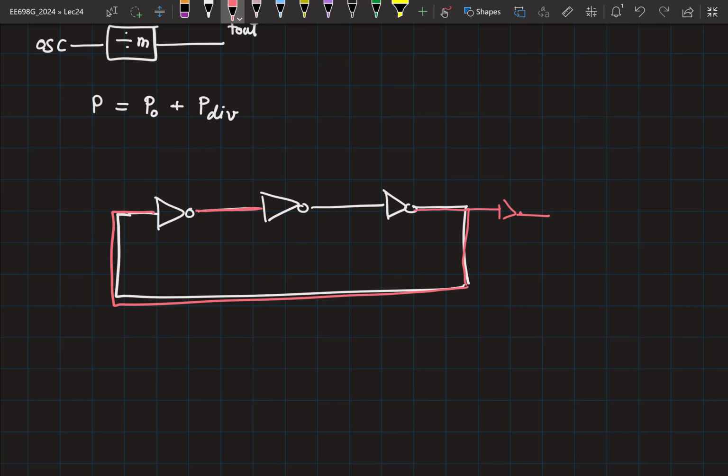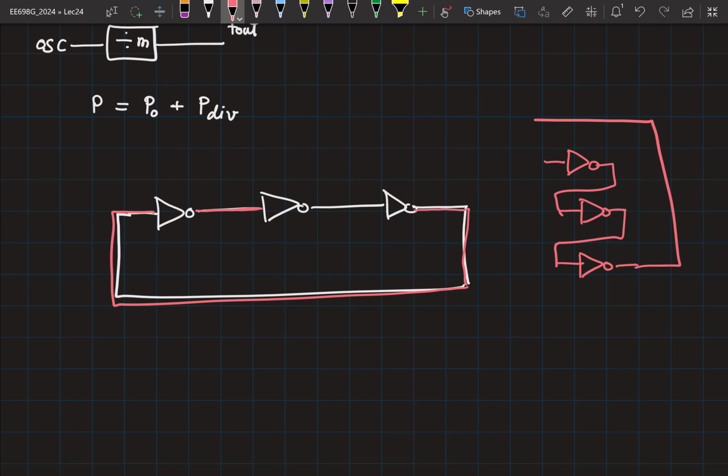It's not that it is impossible. For example, for inductors and very, very specific cases, you can do it, right? But it may not always be possible. So we generally stick to 90-degree routing. Then how would you do this? One by one meaning? Then okay. So now I have to take this and feed it here, right? That will be a longer routing. You are suggesting this, but then this routing is going to be much longer.